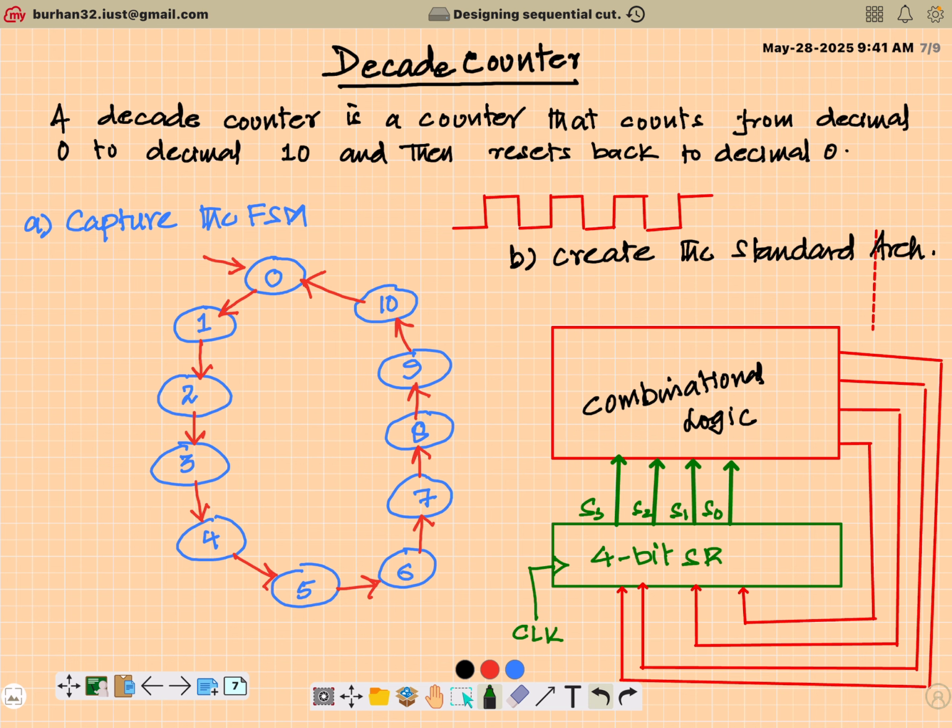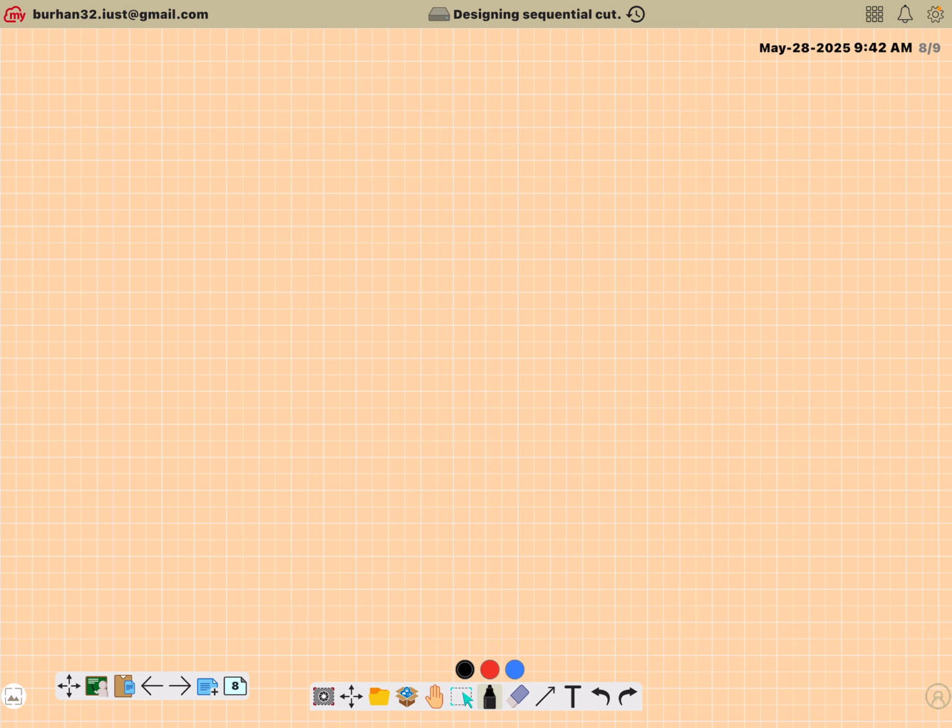So these actually represent the current state of the circuit. And then you can name them next to N3, N2, N1, specifying what will be the next state of the circuit. So this is the second step. We have created a standard architecture in which we have actually resolved this part. Okay, what is the width of my state register? And the third step is that we have to encode the states, because for implementation, we need the states in binary. So third step is